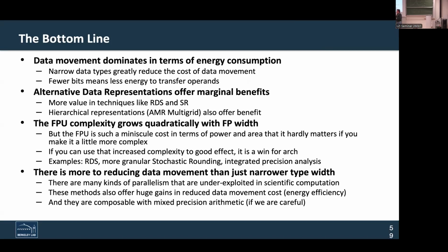So apparently flipping a coin, 50-50, is what you get if your internal-to-the-ALU representation for the number is the same as the operands. The best you can do is 50-50, because internal to the ALU there are no additional bits to tell you whether to bias towards rounding up or rounding down. It's not in the ALU unless the ALU has more bits in its internal representation than you're going to ultimately output.